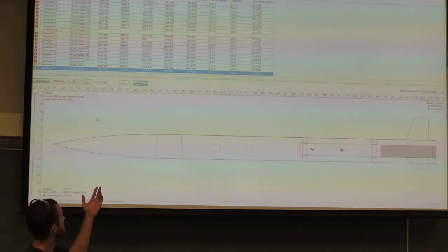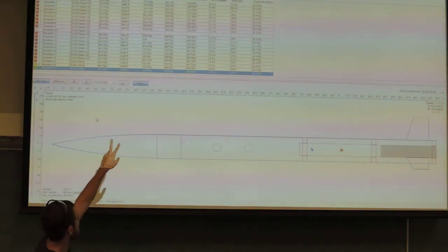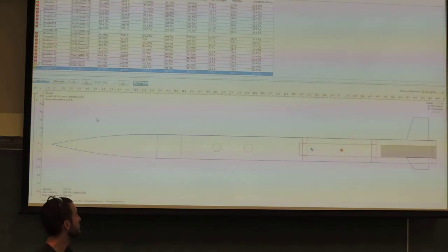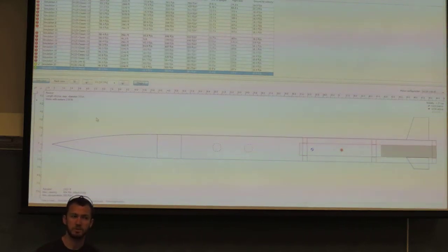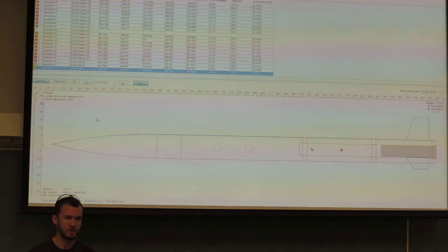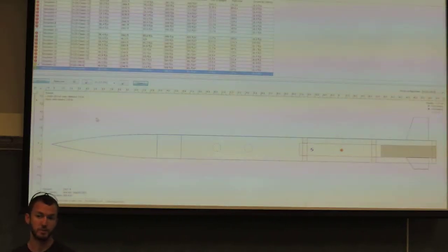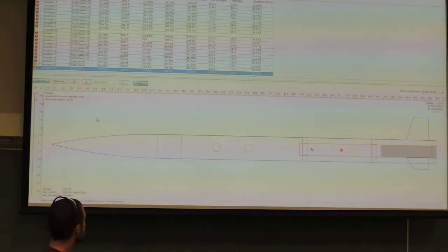So if you're doing these simulations and you see, let's say we flip those two, and you said 555 feet per second was your velocity at deployment, you really think your parachute would do anything? It's just going to get ripped out and then zipper your rocket, so it's just going to basically pull your rocket into pieces, right? So you always want to pay attention there. And max velocity, of course, self-explanatory, max acceleration.